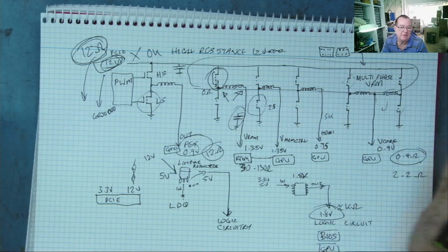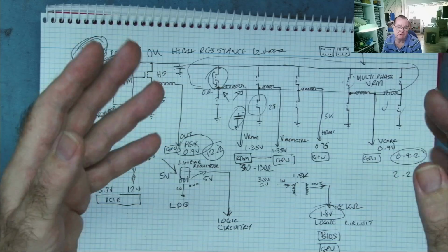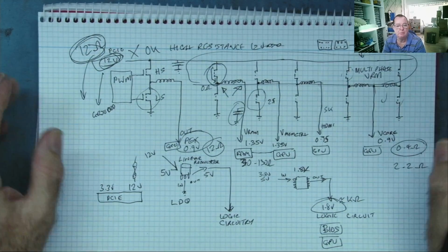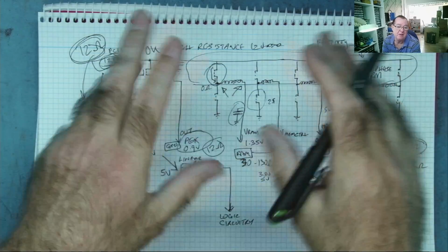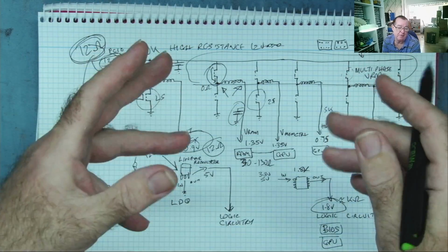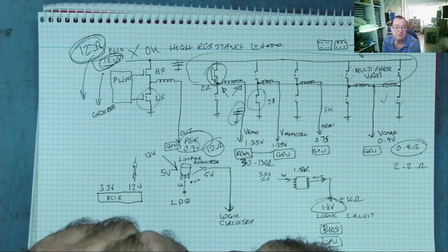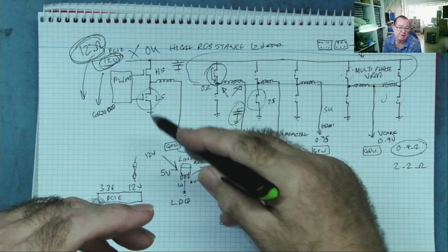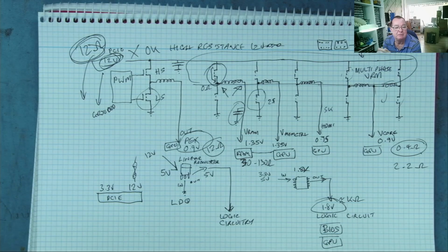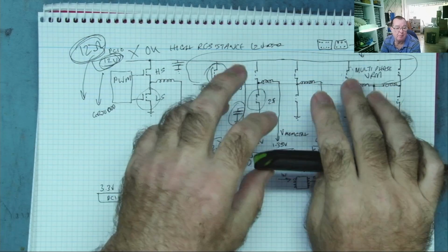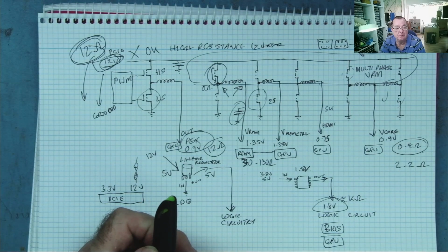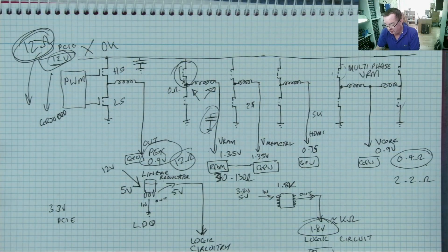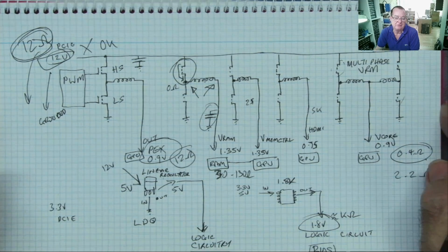Now, I won't go into diagnosis of faults in VRMs in this video. This video is more to help you pin down where the problem is and then zoom in on that area to diagnose further and hopefully fix it. So I've made several videos on short circuit finding and VRMs, and I'll link them in the description to this one. So if you have a problem in that area with shorts, have a look at those videos for more information. Just to finish this video then, let's have a look at a faulty graphics card and take some resistance readings.